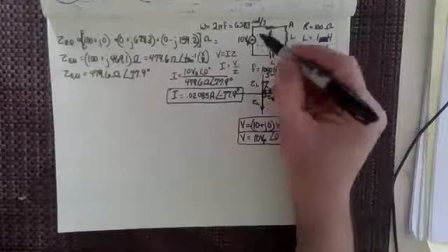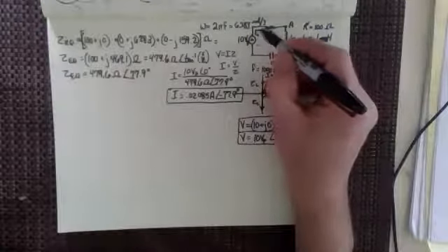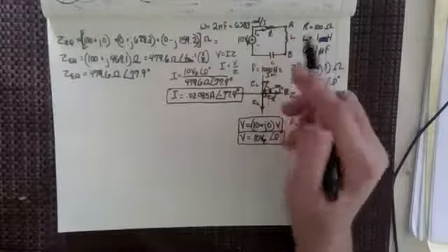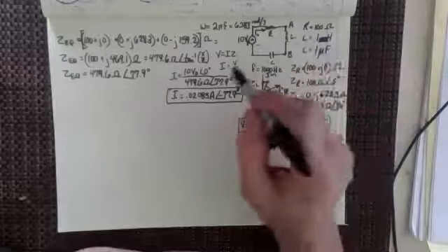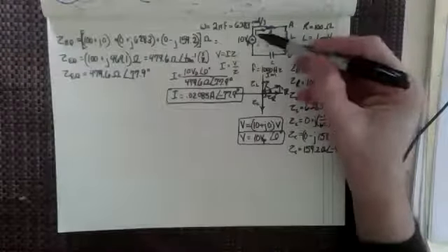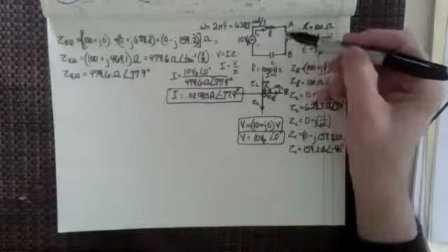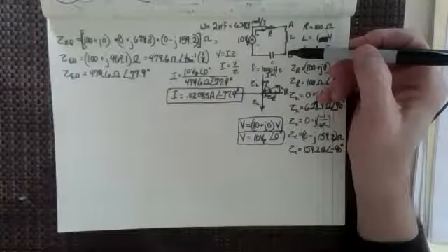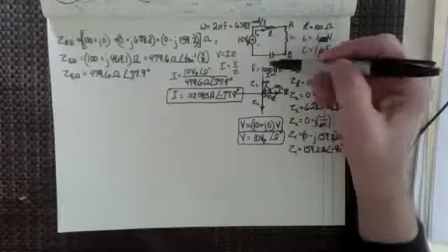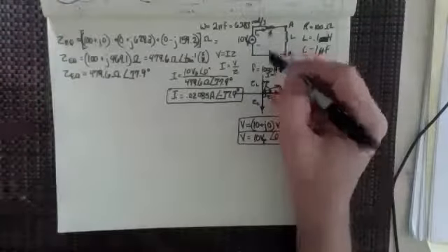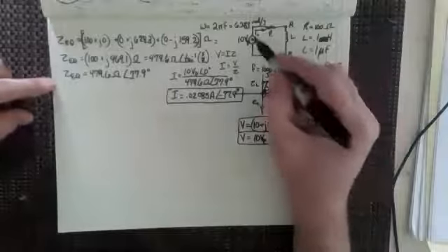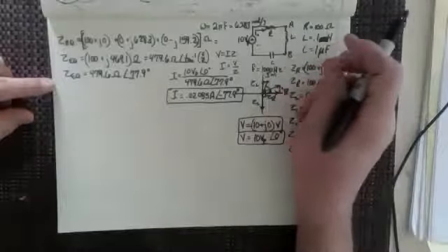And again, we're going to have to look at these. We know that even though under AC the current flows back and forth, we always declare a direction, and that direction is always where that first positive current is going to be flowing. And so if it is a positive current, it's going to be flowing out here. And of course, we know at the second half of the cycle, it goes negative and it'll be flowing the other way, but let's not worry about that. We can do our circuit analysis by looking at the forward flow of that current.